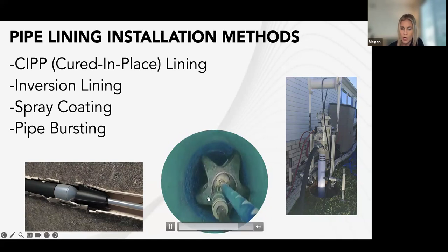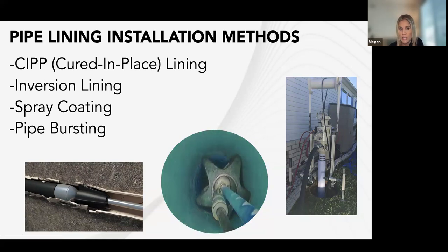There's also spray coat or spray cast coating. And so basically, this is essentially like painting the inside of your pipe. And this is a good application if there are a lot of turns in the system, there's not significant cracks, and it's more of a preventative solution so that the pipe doesn't deteriorate over time. And this is also a similar solution that would be used to line the water pipes. So it's more of a coating, but it's installed a little bit differently.